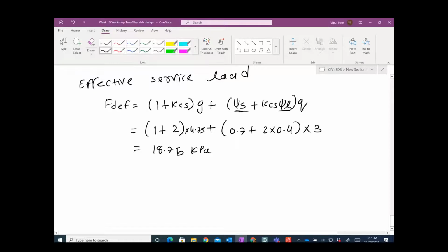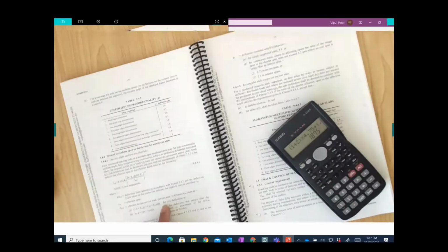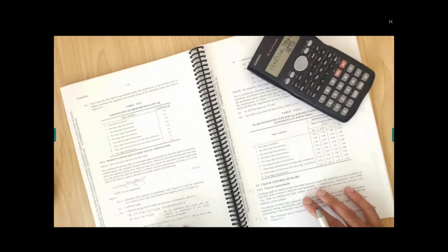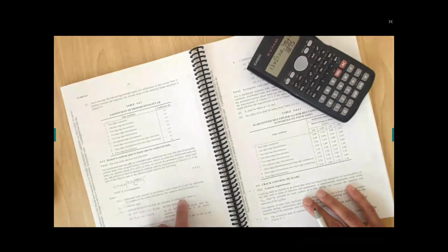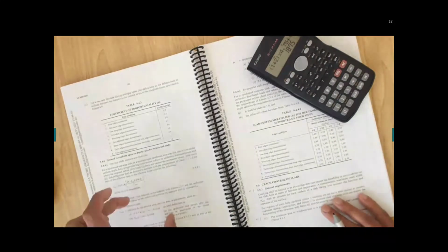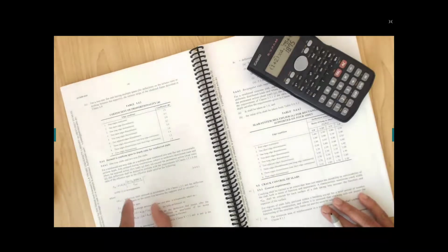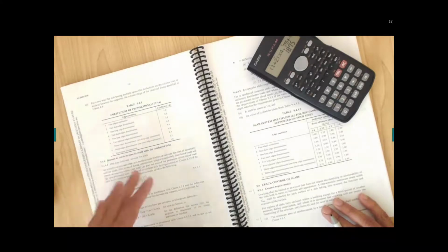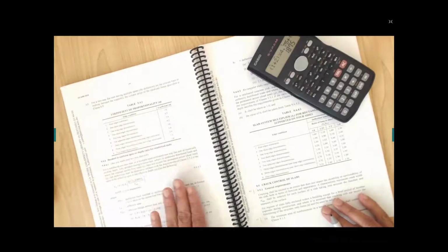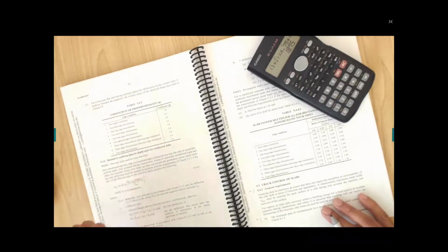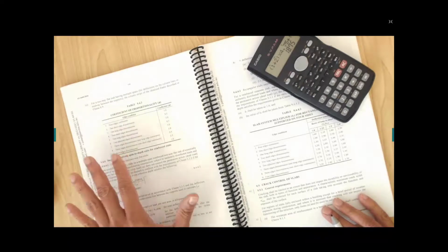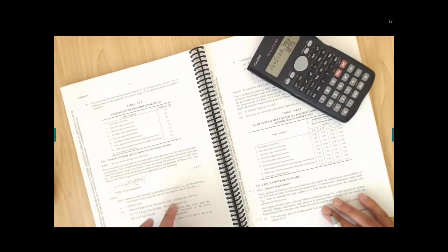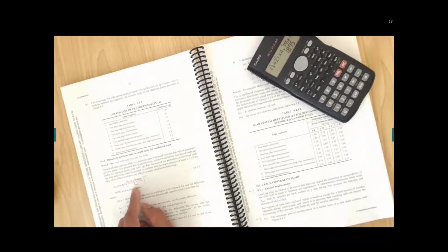And the units, you don't need to change them. Someone might say, let me play with the units. The standards will tell you those units, saying this is in kilopascals, this one in megapascals. Someone might say this is not matching, how come you are putting kilopascal and megapascal? Look, they already multiplied by thousands and so on to take into account kilonewton, so they have already done it for us. So we need not play with the units for these equations. Whatever they said here, we just take it as it is, okay?